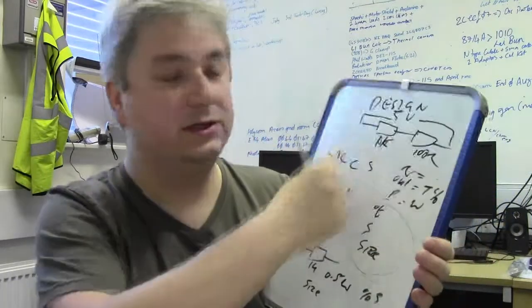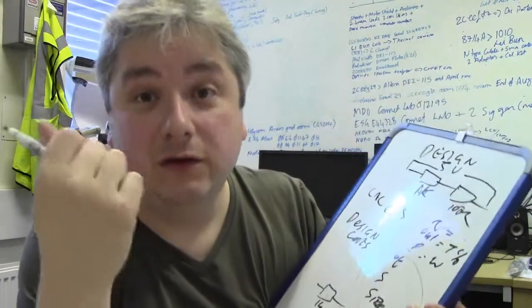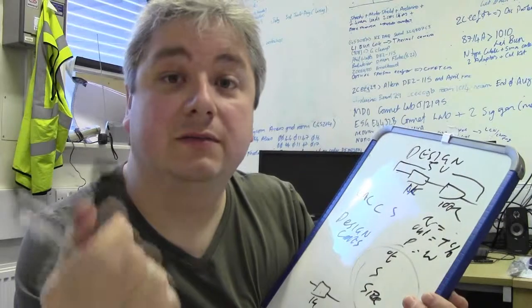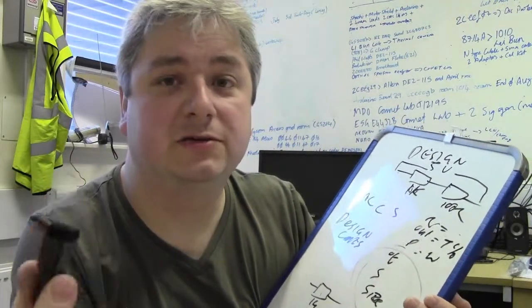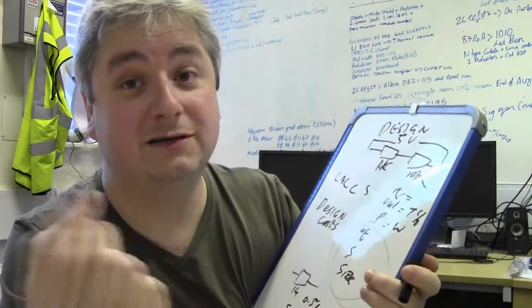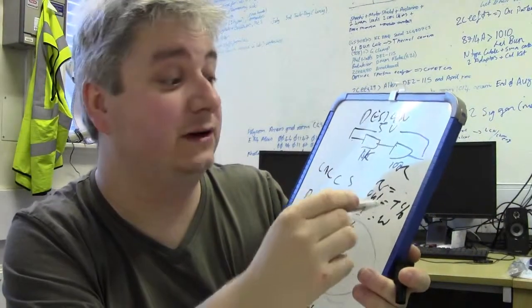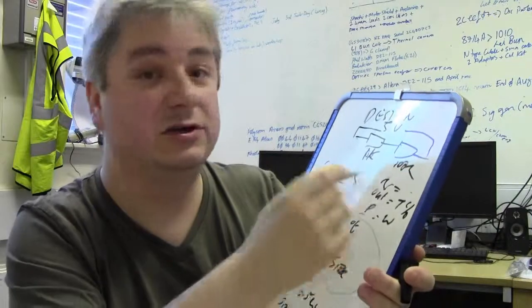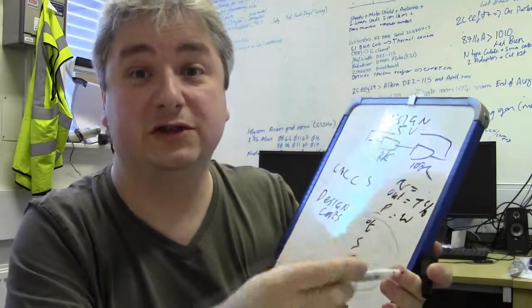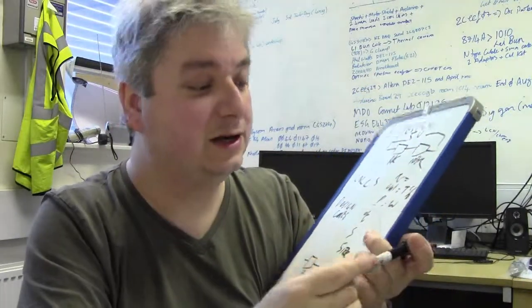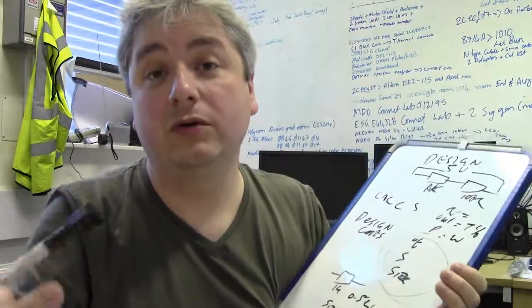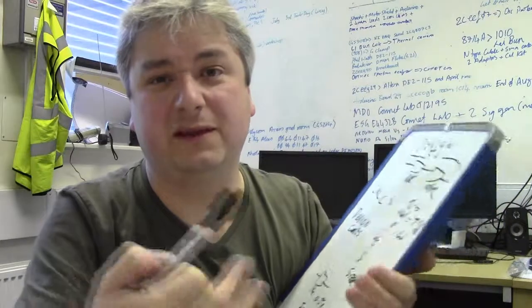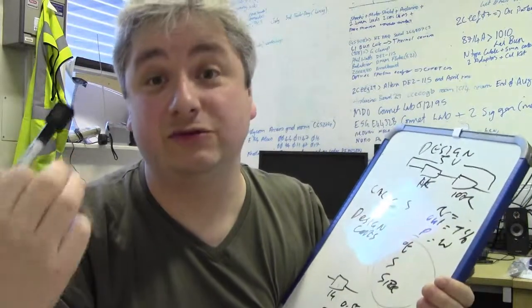Now, if you know all these design characteristics, if you look for your components on places like Farnell or RS and things like that, you can actually do parametric searches based on characteristics. If you've calculated everything out correctly, you can plug in all these values, your tolerance, your resistance, your wattage, your temperature coefficients, things like that. You can even do size and dimensions, and it will slowly filter down all of the components you can buy from them that fit your particular criteria, and that's how you choose.